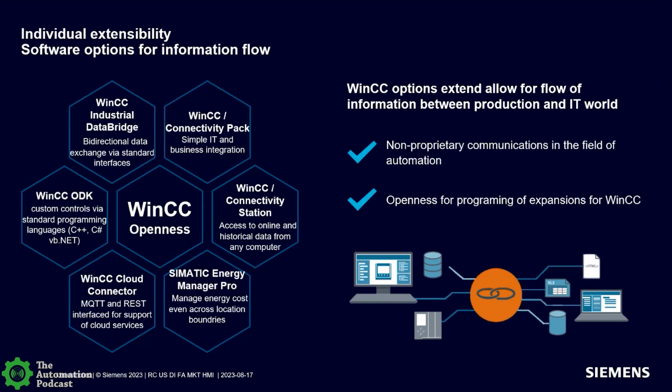WinCC Connectivity Pack is a good way to move data up into other business and IT systems. And it's not a continual database push like Industrial Data Bridge is. It's something where you can specify that you want, at certain times, to send a certain set of data somewhere, or grab data based on, I need to see what happened last week, Wednesday between 2 and 4.